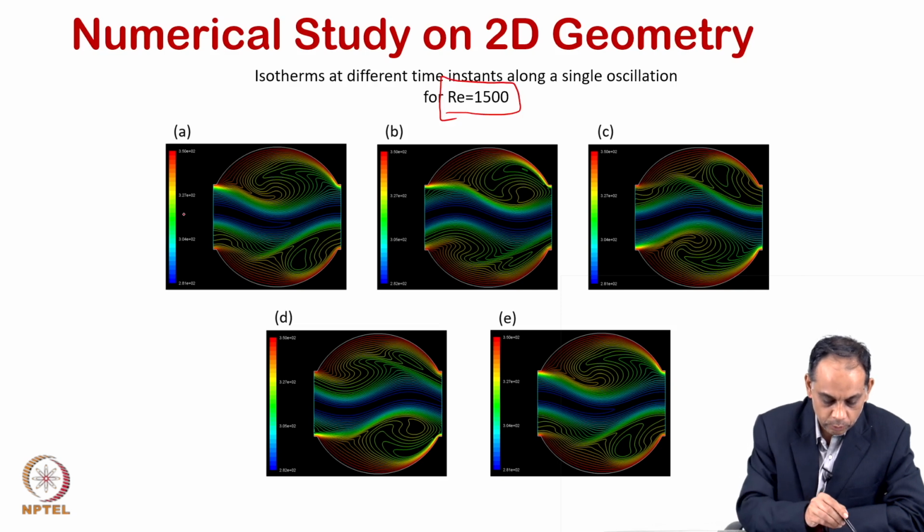What happens is that flow enters, however, because of the separation zone on the top and bottom, the flow is getting diverted and squeezed, and this vortex from the bottom region is shed, and so it squeezes this core flow towards the top side, while the bottom side, the shedding is confined to the top region.